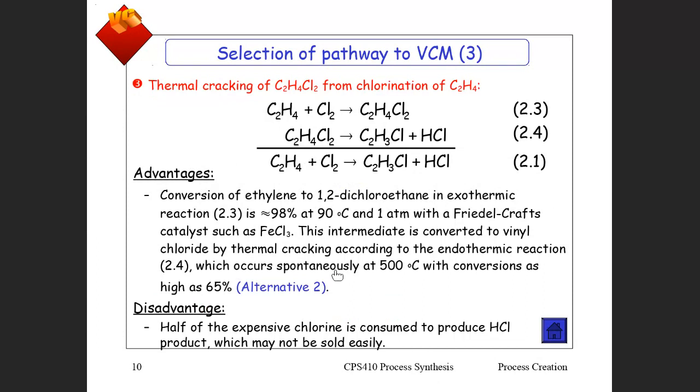Going back to acetylene, this is the reason you've got, when you're using acetylene to cut metal, an acetylene cutting torch. The acetylene line has got a flashback arrestor, so that if the flame goes back into the acetylene line, even without oxygen, it can propagate backwards in the acetylene line into the gas cylinder. So they've got these flashback arrestors in acetylene torches.